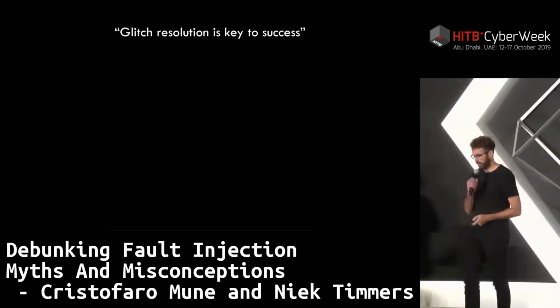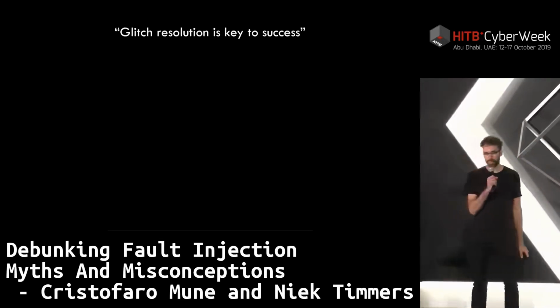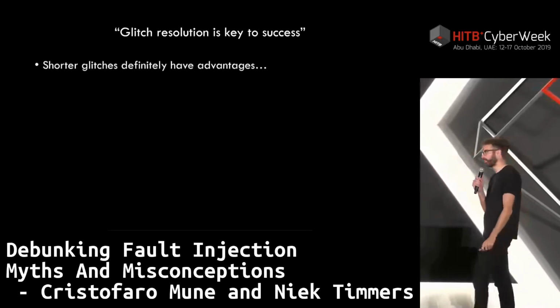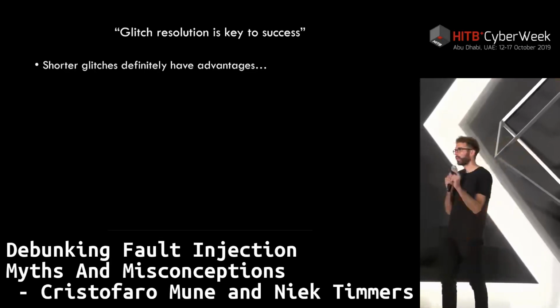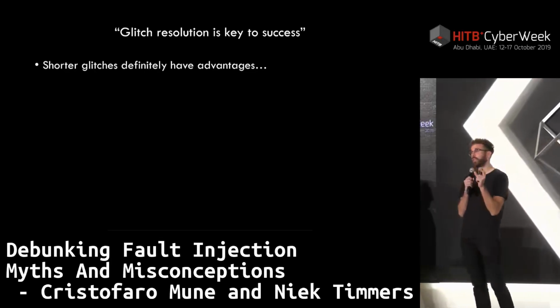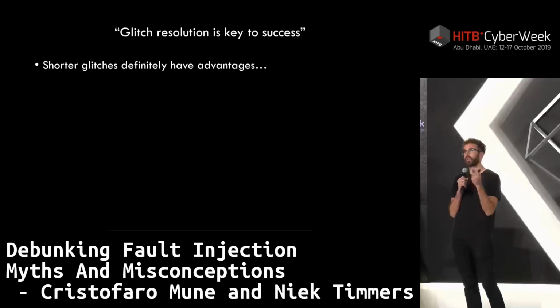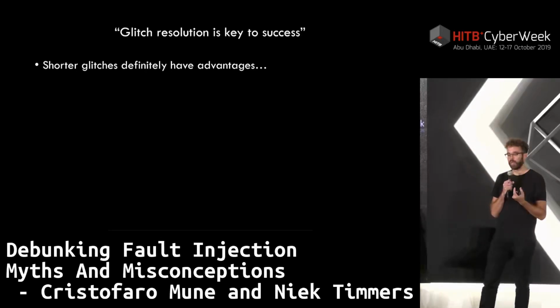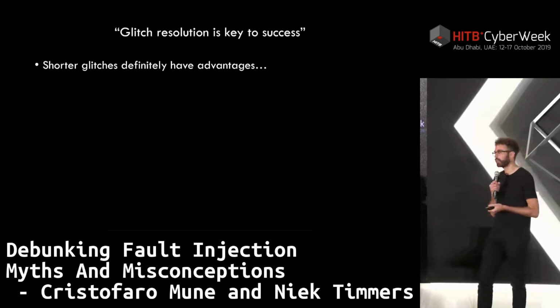Glitch resolution is key to success. So, typically what we hear is that the glitch resolution that you need to have in order to change one instruction or one particular bit in some data field needs to be quite short. And it's true, shorter glitches definitely have some advantages.